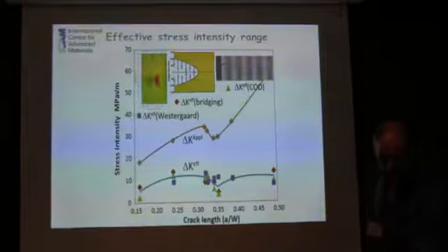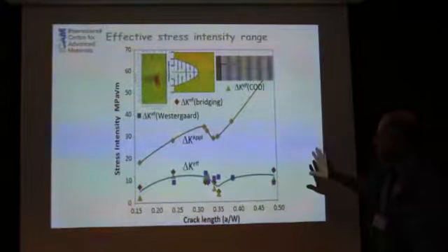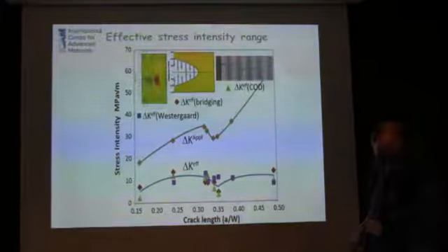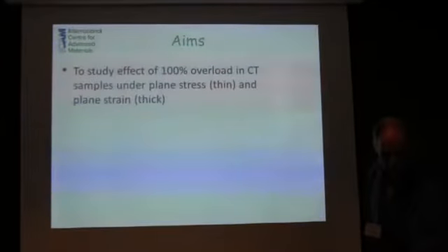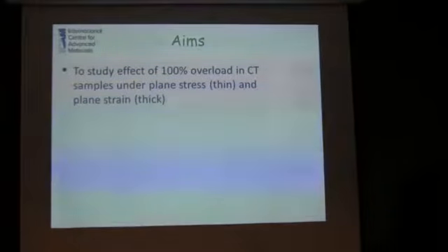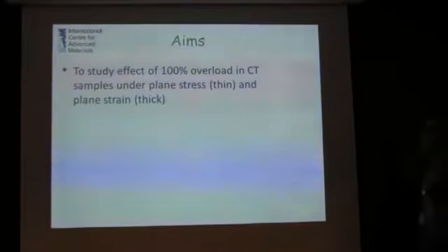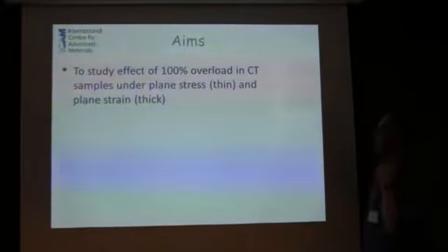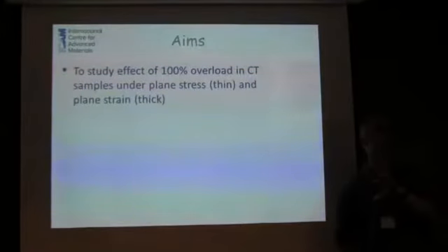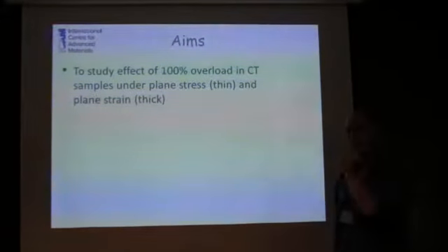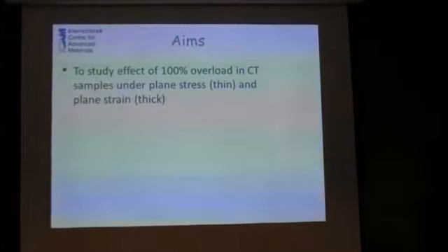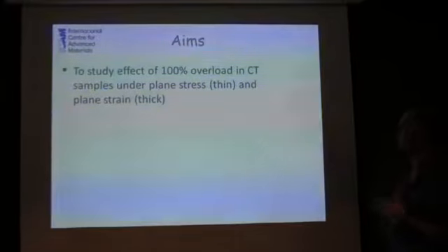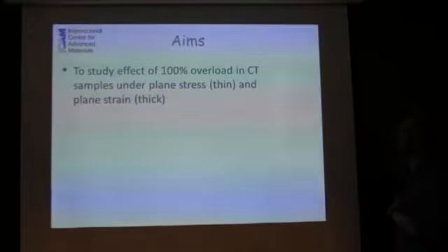So with this tool in mind, in my particular talk I'm going to focus on the diffraction. Jean-Yves focused more on the imaging. So the aim in this talk was really to look at some of the questions that we were set yesterday in the heated discussion relating to closure, to try and understand, are there ways we can start to probe what goes on at that crack tip? Can we see the crack tip? Can we measure the stresses around the crack tip? And can we compare plane stress and plane strain?